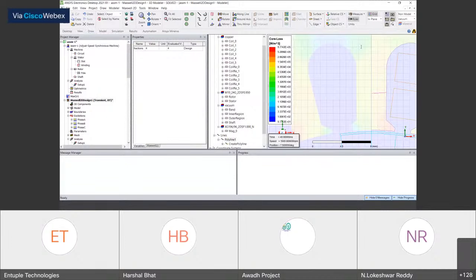Then there's a question if Maxwell can handle multiphysics data. So yeah, when you're coupling Maxwell with multiphysics solvers in Workbench, the solutions from those solvers, well, depending on what solver and what you're solving, if those things are compatible, they can be brought into Maxwell. For example, the temperature you can bring back in Maxwell.